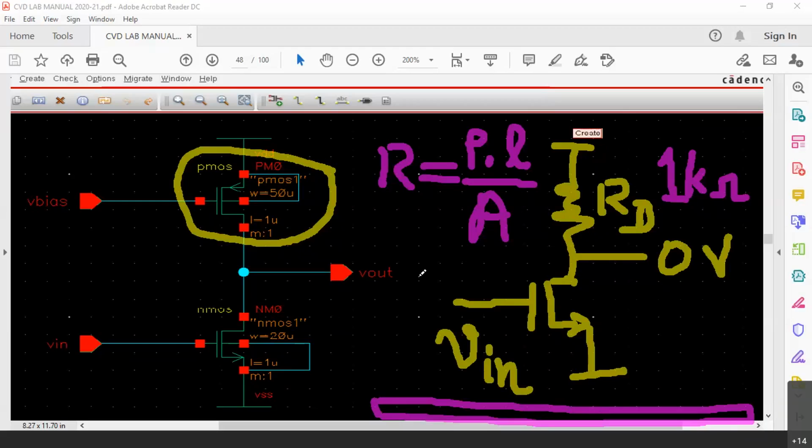Please remember that. In general, people think transistors have a larger area than the passive devices. That is the case with the discrete devices. In the discrete devices, you are seeing a resistor which is small, a ceramic capacitor which is small, and a transistor which is bigger. The transistor is made bigger purposefully so that we can handle it. Otherwise, inside the transistor, it is a small silicon chip again. Only power transistors are made much larger because they have to handle a large amount of current. They have to handle a large amount of power.